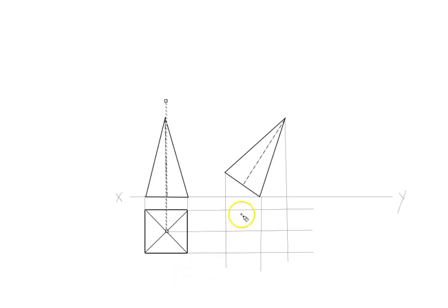Now in our example, this solid is going to get tilted with its base at an angle of, say, 30 degrees with the horizontal plane. So we might mark the angle here, 30 degrees. Then the next step: now we have tilted the position. Whenever we draw projections, the tilting position has to be shown in front and top view to get a complete picture. So we project lines after tilting this solid here.